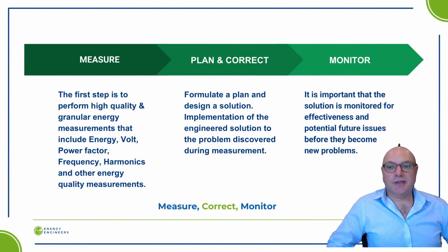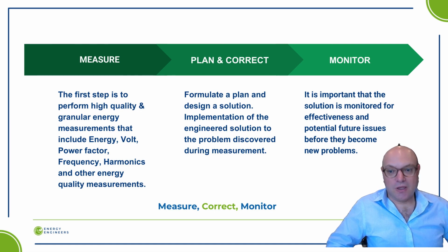Implementing changes. Here's where the rubber hits the road. This is probably the more disruptive part of the process. Here is where the solutions to peak demand and power factor will be implemented: peak technologies to move or remove peak demand, energy storage, energy efficiency upgrades, and/or power factor correction solutions. Yes, power factor correction can lower your peak demand.